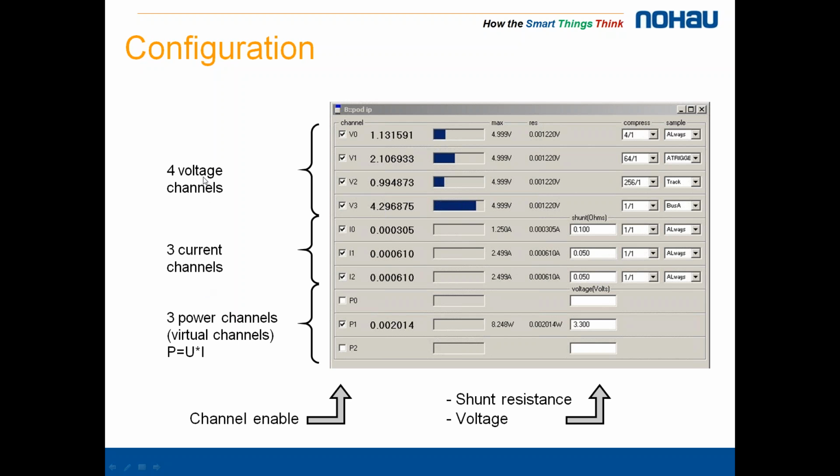And then, of course, when I have both the voltage and the current, then I can measure the power. Because the power is the voltage multiplied by the current. So then if I measure P1, for instance, I can get the current from I1, and then I can either say that, okay, I have a static voltage, so I'm not changing the voltage of my target, which you then put 3.3, or you can use V1 as an input parameter. So if you have a dynamic change of the voltage, you can get this in your power measurements and get the time plot out of that.